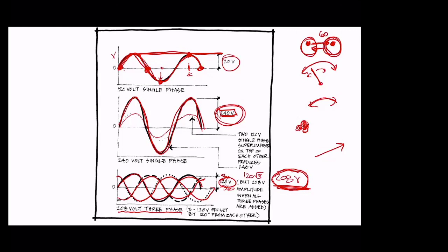If you look at your charger right now, it has a big lump in it, like a python that swallowed a pig. Sometimes the lump is halfway between, sometimes it's all the way on one end near where you plug it in, like on Apple products. If you look at the fine print, you can see the transformer has this much voltage coming in and this much voltage going out. The alternating current goes in at 120 volts. But if you take the effort and look at it now, you'll see the transformer actually has a range of voltages. That's because people get really upset when they plug in their computer in Europe and it breaks. So you can make equipment that works with a range of voltages. It probably says 100 to 240 volts, or maybe 120 to 240, so it can handle anything down to 100 or up to 240, and that way, if you plug it in Europe, it won't break your computer.